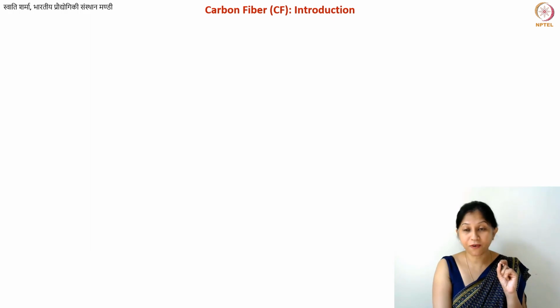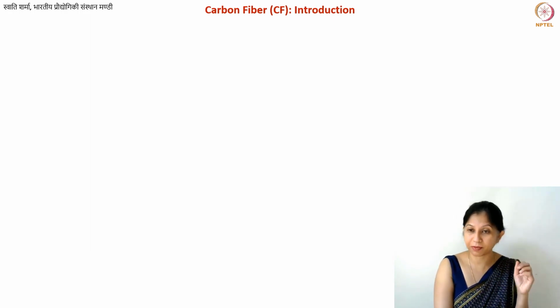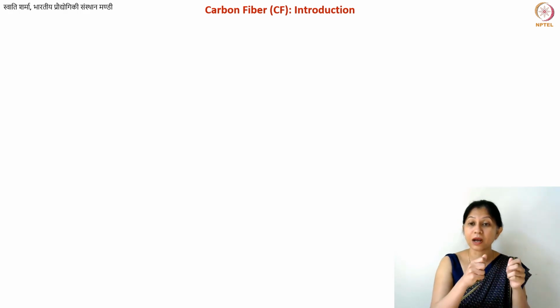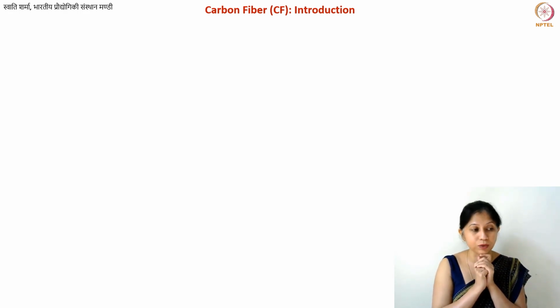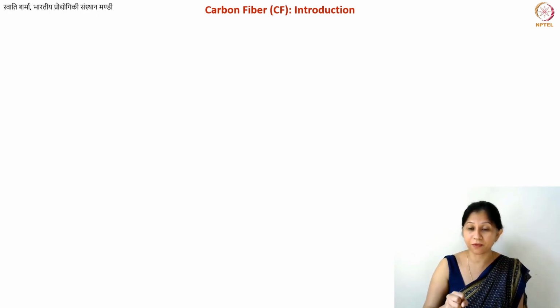You know that carbon fibers, when they are manufactured in bulk, because obviously you need a lot of fibers, you will perform braiding of these fibers, or you weave cloth-like structures out of these fibers. Now these woven carbon fiber mats are used as sheets when we prepare laminates, and that is how we make composite materials. So these are prepared in bulk quantities, for large scale applications, large scale structures. But we also have the diameters of individual carbon fibers in the micro, or sometimes even in the nanoscale. So that is why I'm saying that these can be very important interfaces.